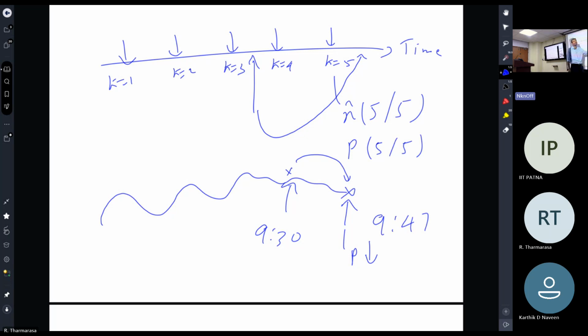Because you can't use a Kalman filter, because in a Kalman filter, you can do that only if your previous state is somewhere here. If you think about T, capital T is like a negative value, right? Time. So that you can't handle with a normal Kalman filter. So you don't update with the Kalman filter. Now the question is, how to use this information to update that state? That is the out-of-sequence measurement.